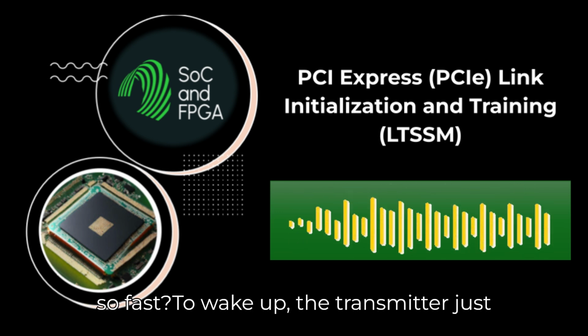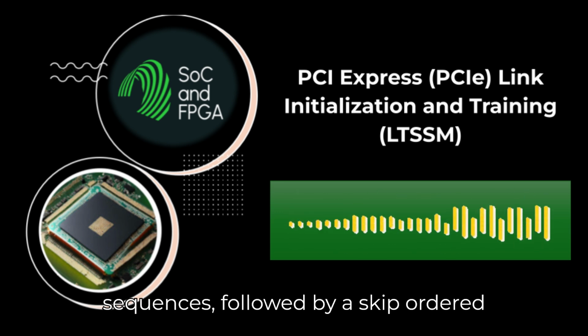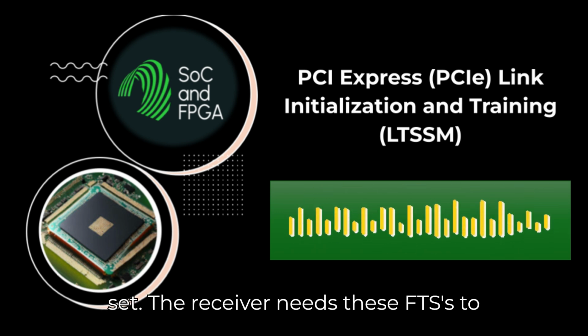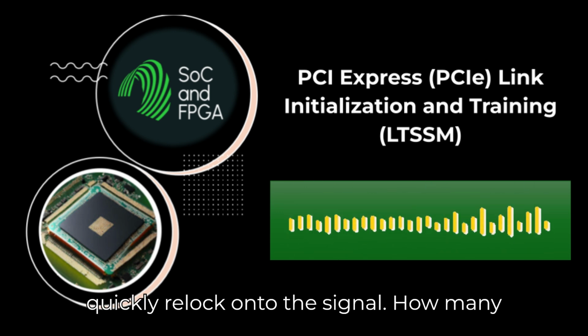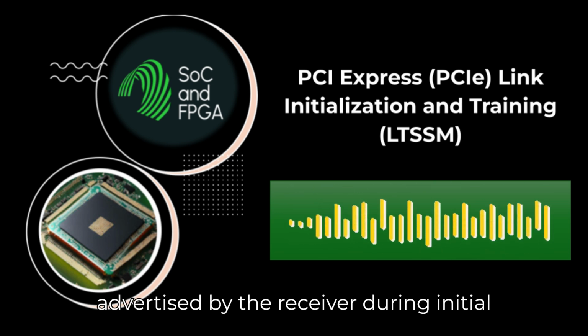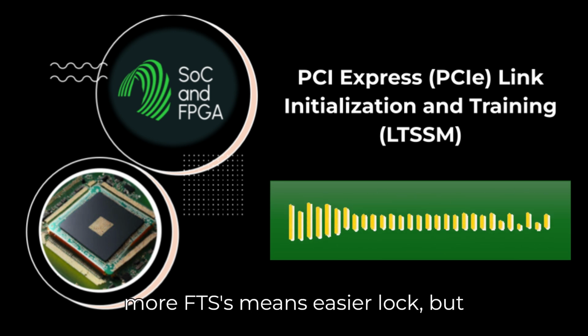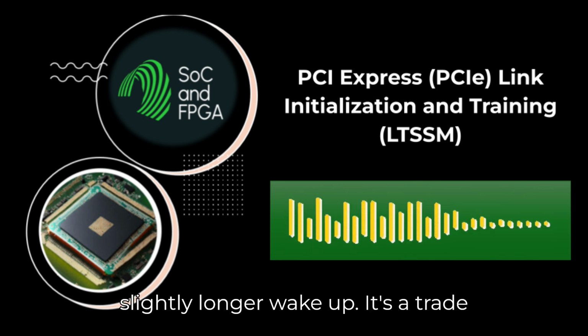How does it wake up so fast? To wake up, the transmitter just needs to send a specific number of special patterns called FTS, fast training sequences, followed by a skip ordered set. The receiver needs these FTSs to quickly relock onto the signal. How many FTSs are needed? N_FTS is actually advertised by the receiver during initial training. The receiver says how long the wake-up call needs to be. Pretty much. More FTSs means easier lock, but slightly longer wake-up.